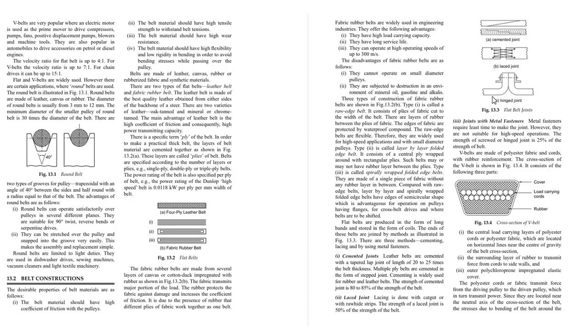So there are three common methods which are utilized for flat belt joints. First is the cemented joint, in which you cut the edges of the two belts and join them in this way, or you can prefer this stepped type of joint. This joint is called a cemented joint, while the lace joint is preferred where you are going to tie the belts on a pulley. Here we are using threads which are weaving over the belts. Then you can use the hinged joint, with metal fasteners, which requires the least time to make. However, they are not suitable for high-speed operation.